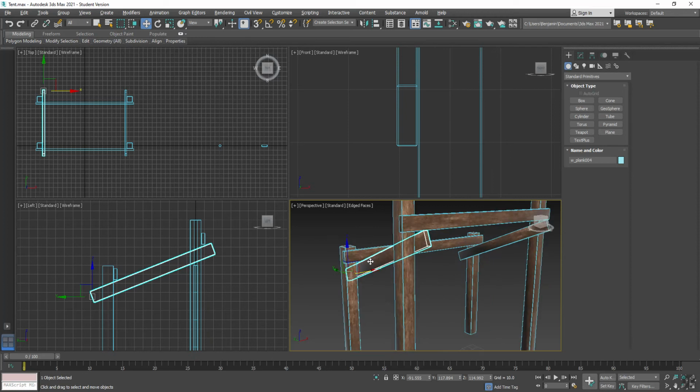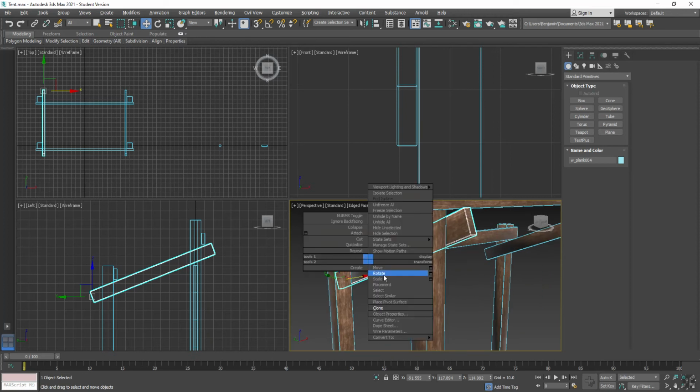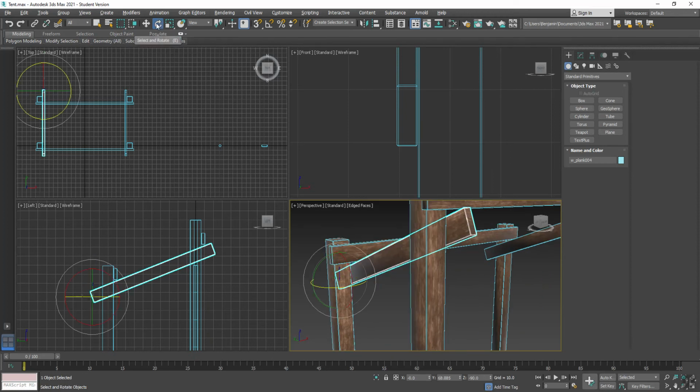Him I'm going to select, and I'm going to go into rotate, but here as well, on rotate, I need to switch from view to local, and I'm going to rotate that 180 degrees. Oops. Let's turn on our angle snap. That'll make it easier. Angle snap, as always, is right up here. You can hit A to turn that on. There we go. Rotate that 180.